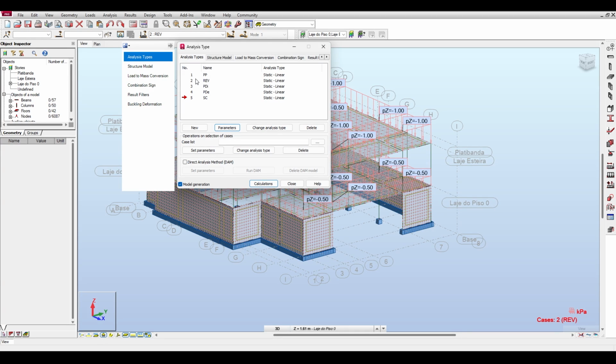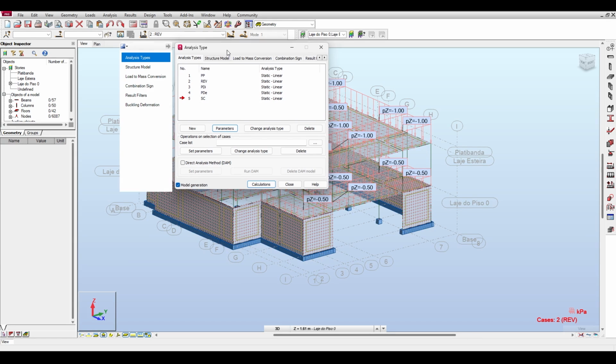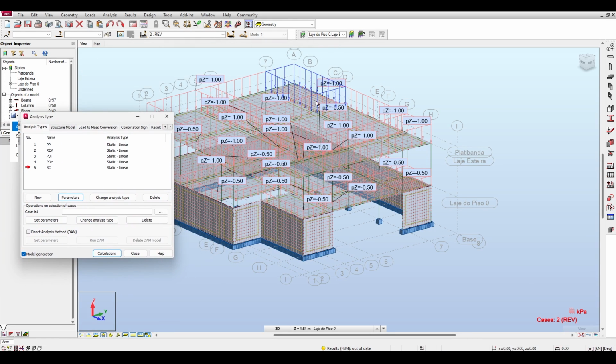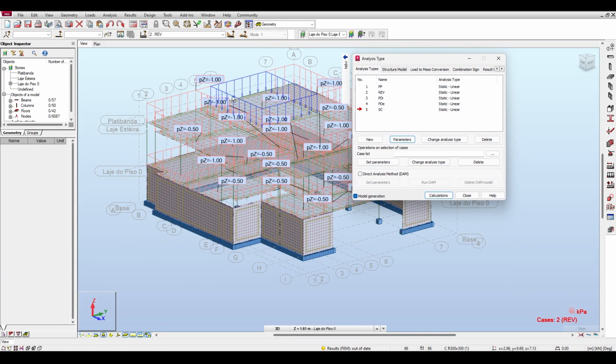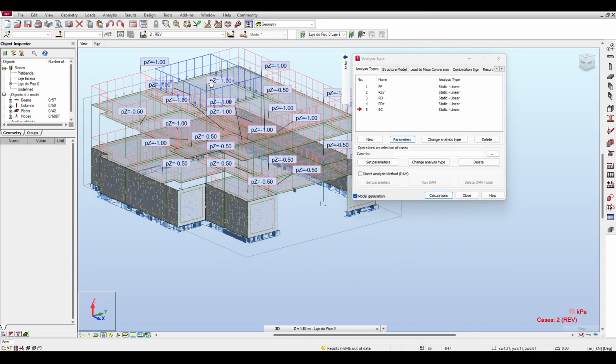But wait, before you define a modal analysis, you need to remember from your structures courses that a modal analysis means the solution of something called the eigenvalue problem. And the eigenvalue problem is a relationship between the stiffness and the mass. So in the eigenvalue problem, you have a stiffness and you have a mass. For the stiffness, that's easy. You have this structure that will have a stiffness. For the mass, you would think, well, that's easy because I can just take the mass of the structure.